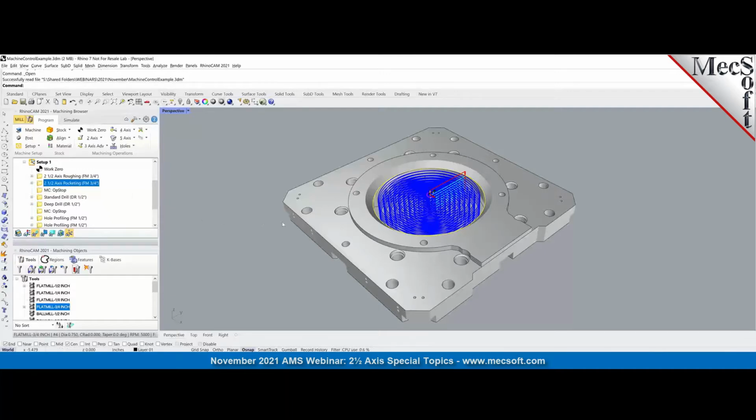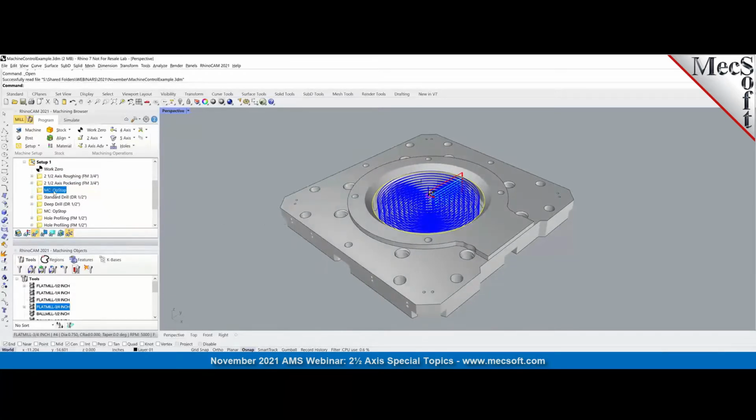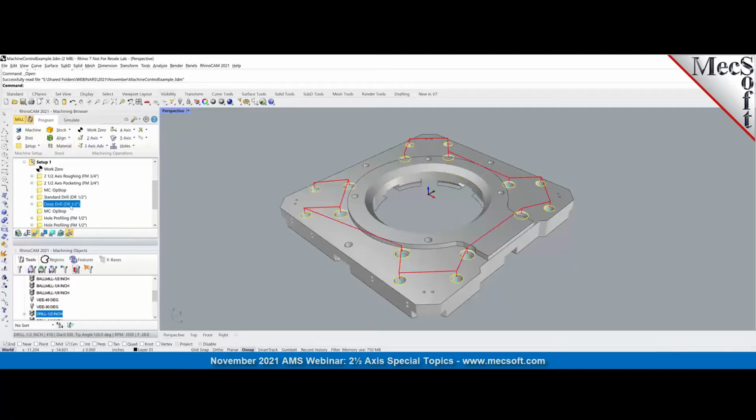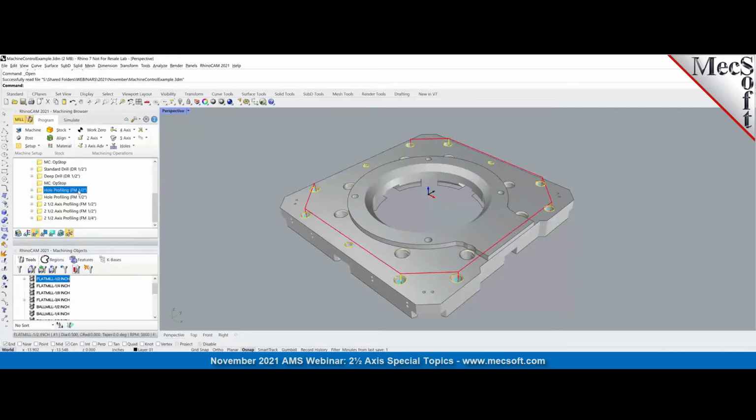And then to introduce the actual manual tool change, we have introduced a machine control operation. Then the tool is changed, and then we have the 1/2-inch drill to do the drilling operation. Once the drilling operations are done, we create another op stop operation and then go into the final tool, which is a 1/2-inch flat end mill, to do all the other operations.